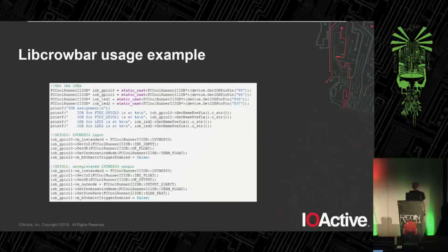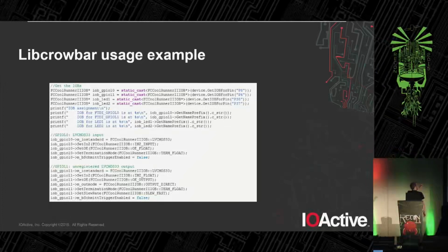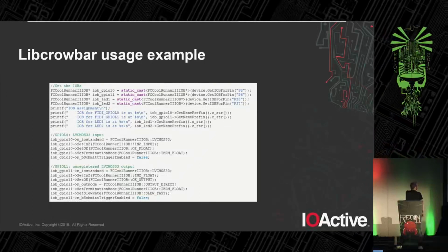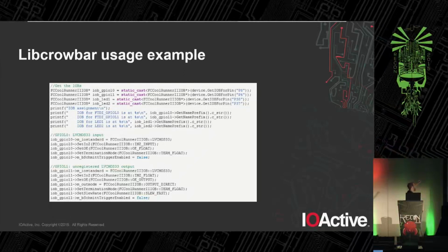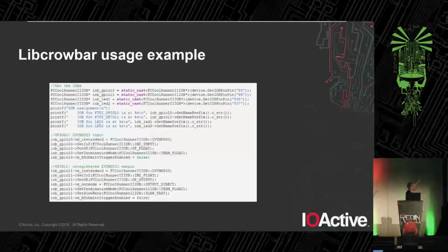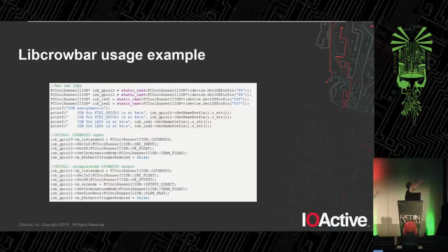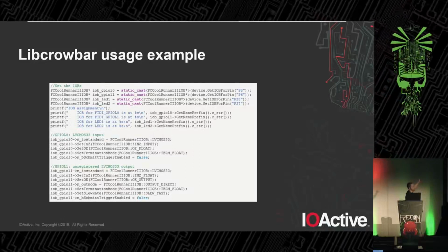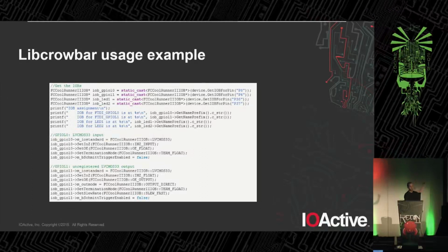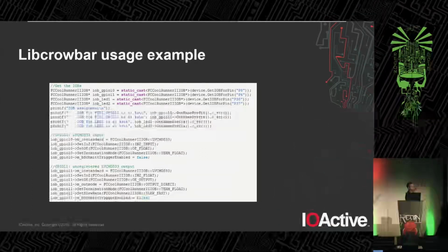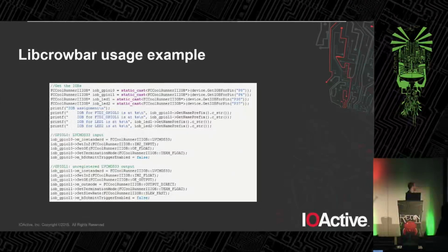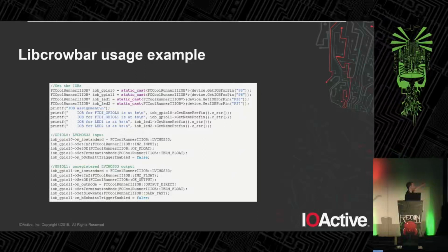So we have a bunch of I/O pins. We select P8, P6, P38, P37, whatever. Then we get the IOBs for each of these. We can now select the I/O standards, some output enables. We're not going to use termination. We're not going to use Schmitt trigger. These are all bits in the macrocell that I was able to figure out. There are still quite a few related to clocking that remain unknown at this point. And then there's quite a bit more going on below this.